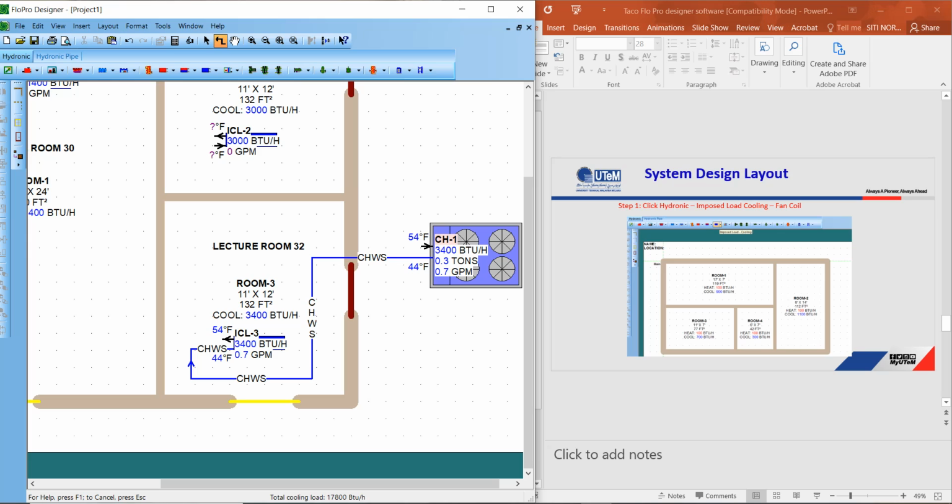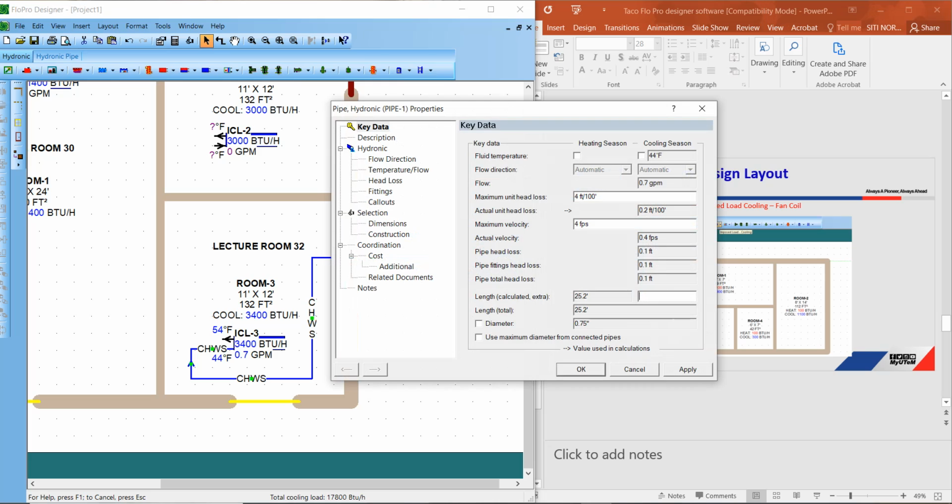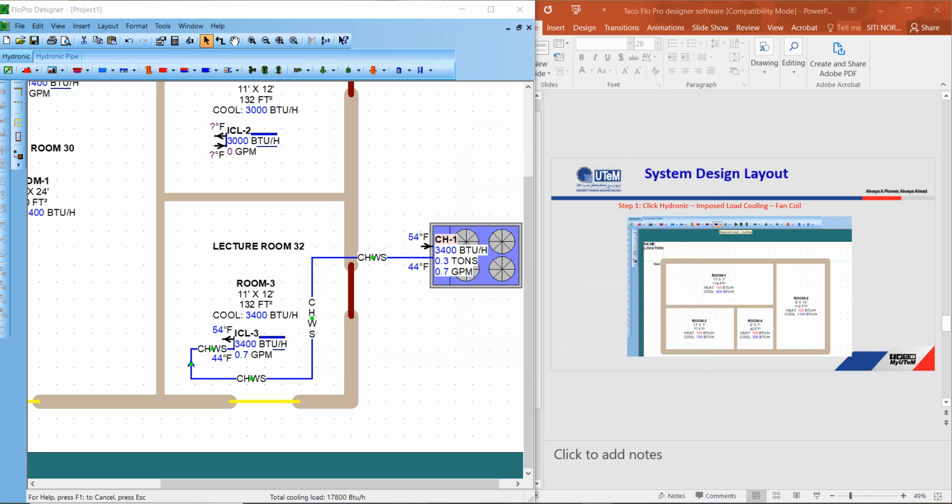Let's say back, escape first. Let's say I'm doing the wrong connection. I delete that line just now. Can I do the wrong connection? Hydronic out and hydronic out. The line will become like this: dot, dot, dot, dash line, dash line. This means a mistake. Control Z. Okay, do the connection again.